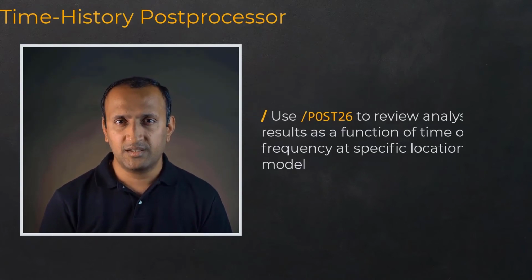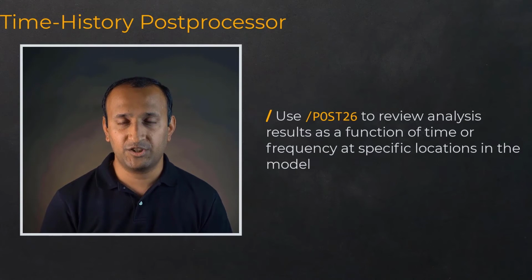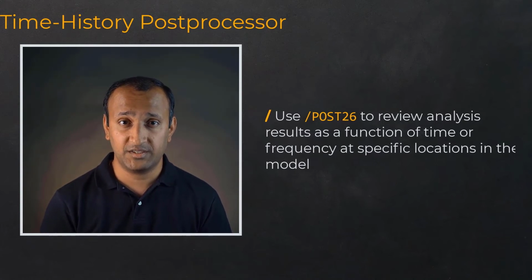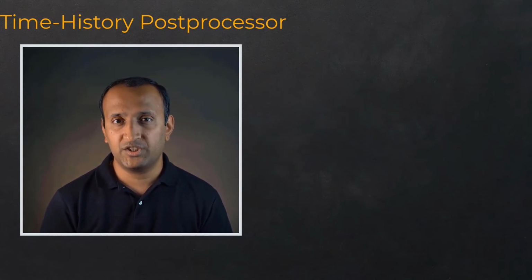Next, let's talk about POST26. POST26 is used to review analysis results as a function of time or frequency at specific locations in the model. One can generate XY plots, tabular listings, or perform math operations on datasets.